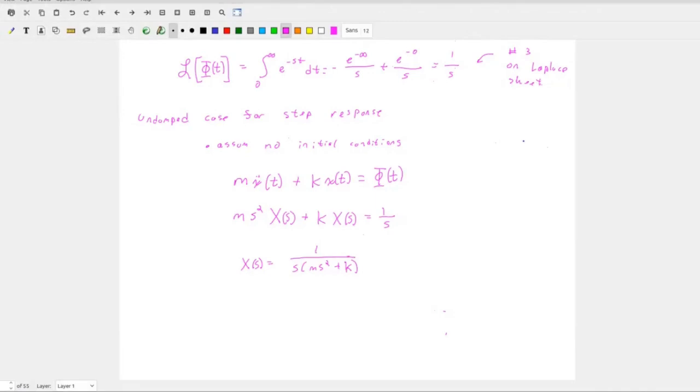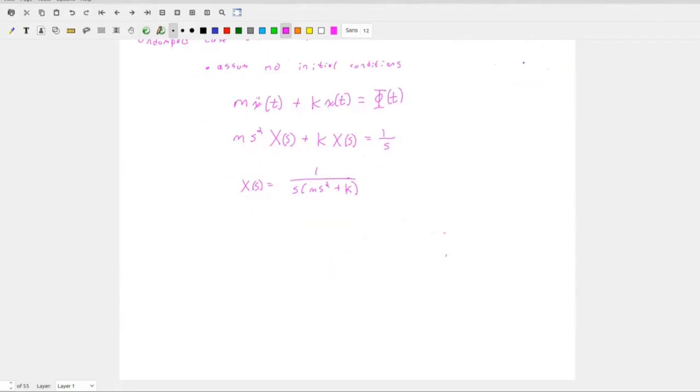Yeah, so we don't have the Laplace in terms of k and m, we have them in terms of omega. So we need to pull out our mass, so it's easy enough to pull out of the first term. If we pull it out of the second term, we can do that by just leaving behind an omega. So we're going to get X of s is equal to 1 over m, I'm going to pull that out completely on its own, times 1 over s times s squared plus omega n squared.